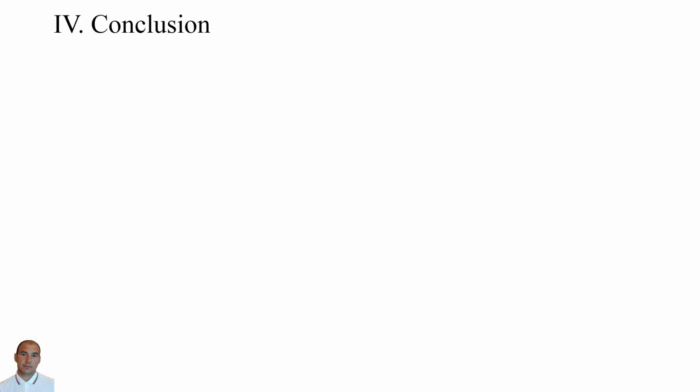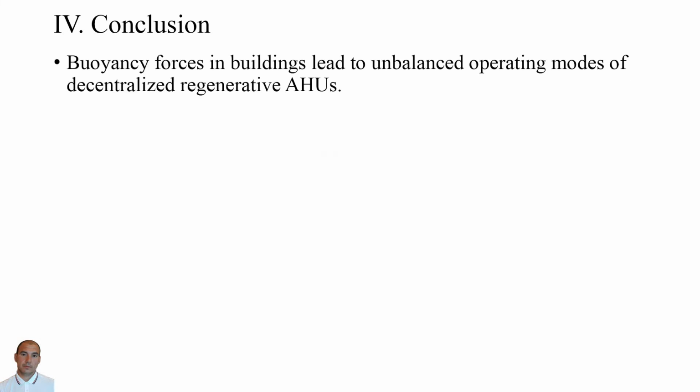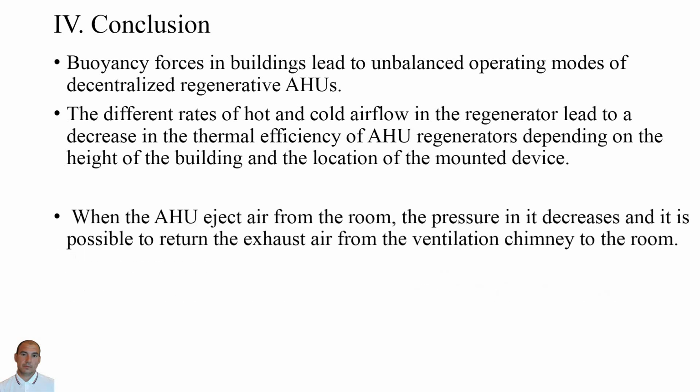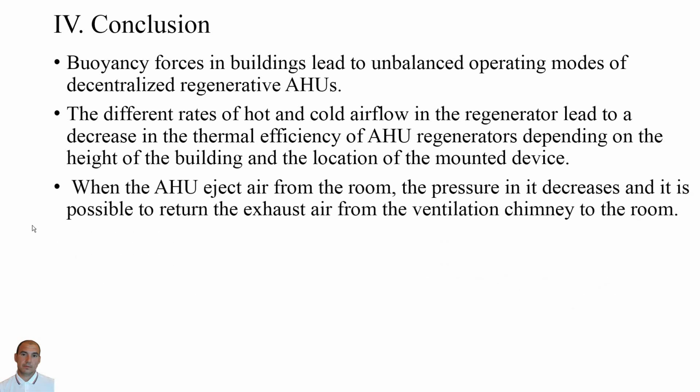The conclusions of this article are written on the slide. Buoyancy forces in buildings lead to unbalanced operating modes of decentralized regenerative air handling units. The different rates of hot and cold airflow in the regenerator lead to a decrease in the thermal efficiency of air handling unit regenerators depending on the height of the building and the location of the mounting device.